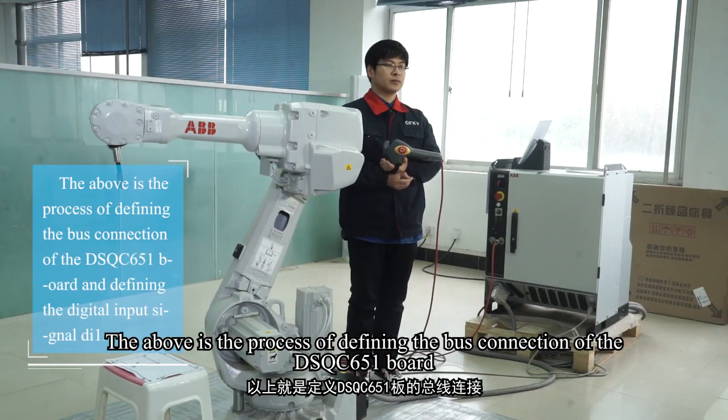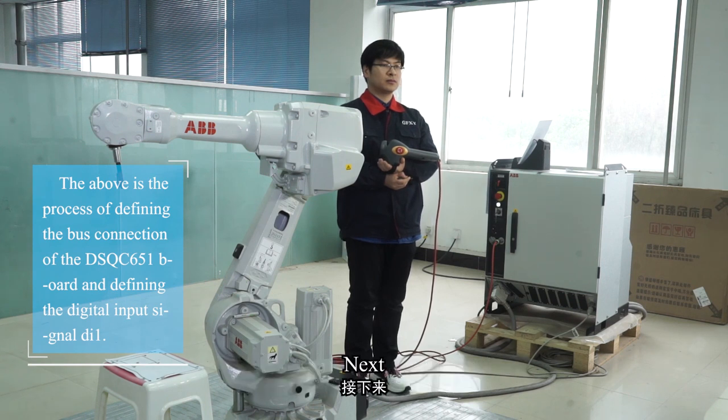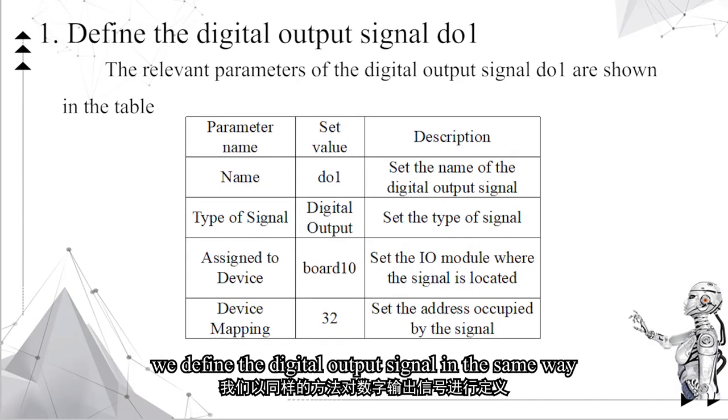The above is the process of defining the bus connection of the DSQC651 board and defining the digital input signal DI1. Next, according to the above method, we define the digital output signal in the same way.